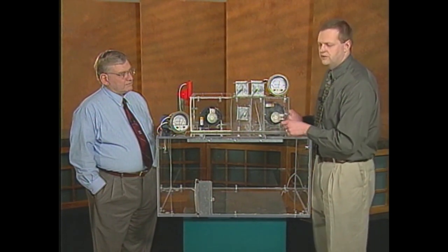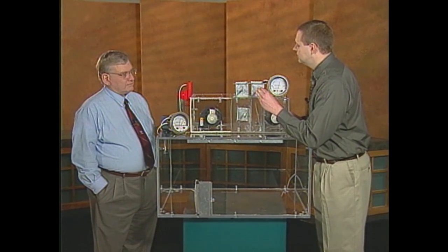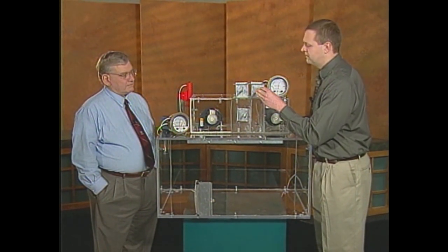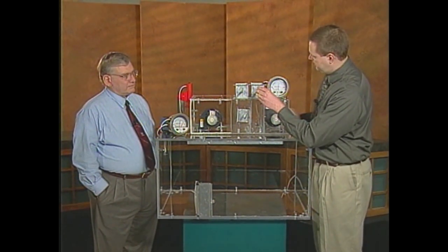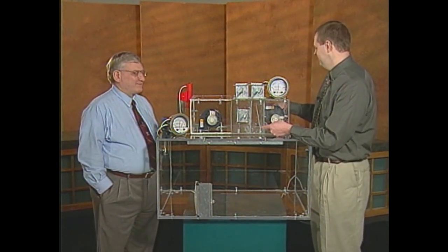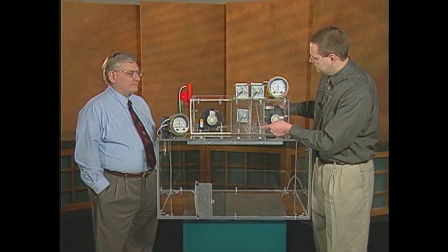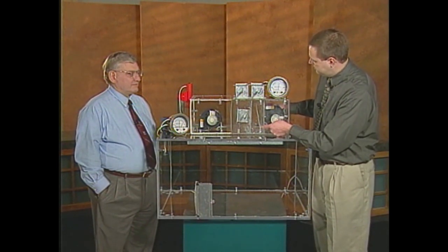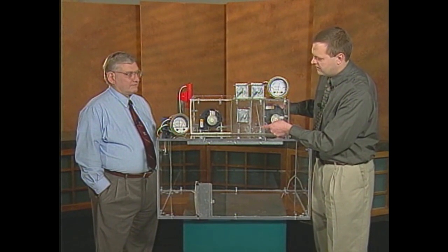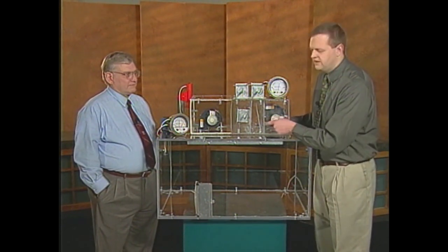What we see over on the building pressure gauge is it went back up again. So we need to relieve a little bit more air, open up our relief damper a little bit more, which causes our pressure in the return air plenum to go down again, and speed up the return fan. So eventually you can get to a balance point where you're within your set point range on building pressure and you're maintaining your set point in your return air plenum. Just takes a little bit of work.